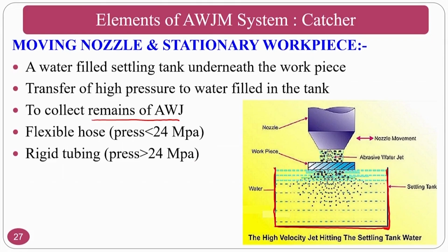So, if you go anytime for quality improvement programs or any other things, if you are a PhD student or master student, try to work in the advanced areas, and you can go for micro cutting as well as texturing with these jets. Okay. If you want to go for this type of moving nozzle and stationary workpiece, you just put the water tank with water. Because of the water, when the water jet comes, it will be caught, and the water has certain resistance to the jet. So, this water jet will die off once it enters the tank.